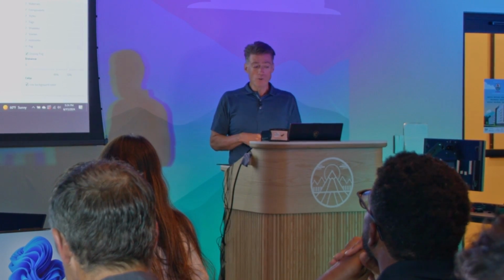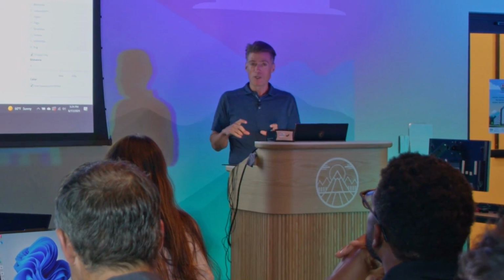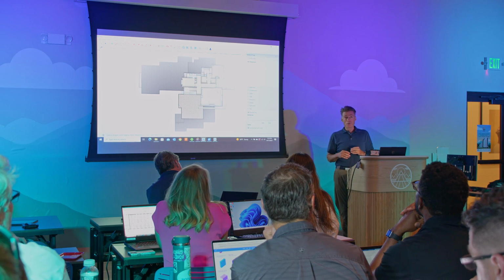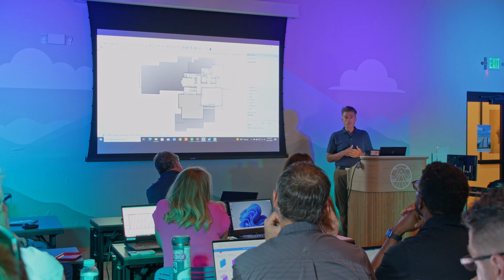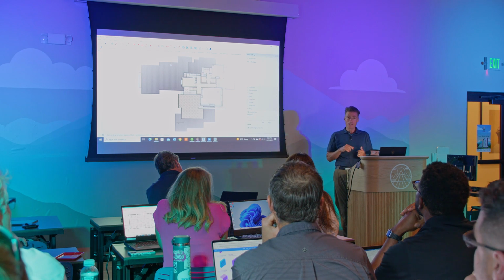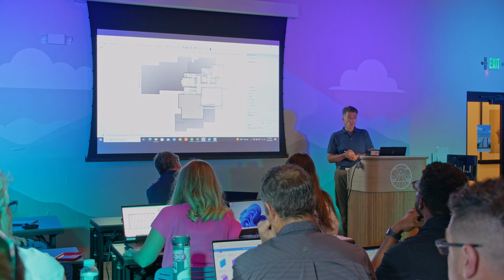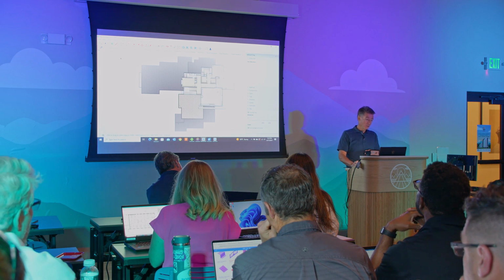And I will also use it for certain exterior trim when I have a unique profile, like on this house, that profile that wraps around. The reason I like it is because it creates a solid. If I just do individual trim, a lot of times I end up with not a solid and I have to go back in and put the other side on.